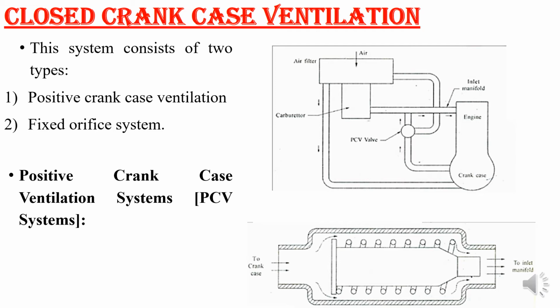So when the engine is running, some unburned fuel and combustion products will leak past the piston and move into the crankcase. Sometimes combustion products and HC emissions that are there in your combustion, due to the gap and clearance volume, will sometimes come to your crankcase. This leakage from the combustion chamber to the crankcase is called blow-by gas. This blow-by must also be removed from the crankcase, otherwise it is dangerous for your engine.